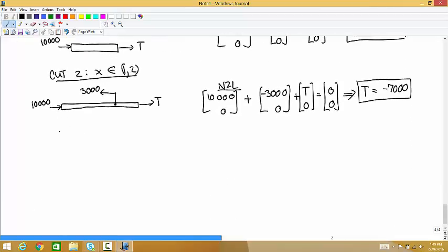All right, so now the elongation. I wrote it before as a displacement. I'm probably a lot of times going to write it as a delta, like a change in length. But anyways, it's equal to T1 times the length of 1 over EA plus T2 times the length of 2 over EA.